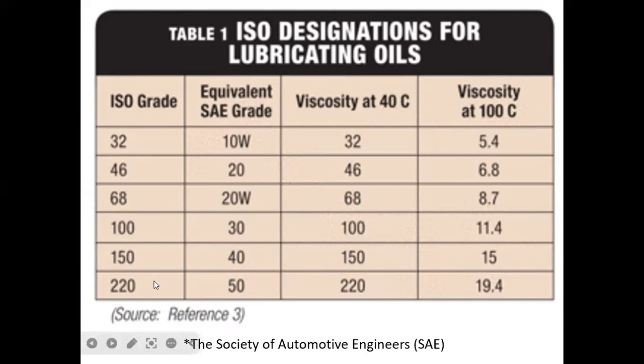And lastly, if you examine ISO grade 220, it is equivalent to SAE grade 50. The viscosity at 40 degrees Celsius is also 220, as you can see here at the last row, column 3 of the table.